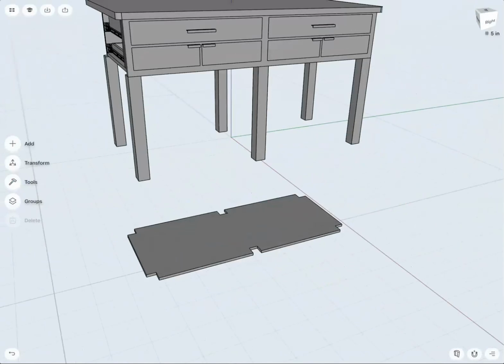Then they could go to a draftsman who can load the file, and they have 2 ways to create them. In my own professional work, we don't use that anymore. We just put the step file into a CAM program, and then via CNC milling, we simply cut all the individual parts out.